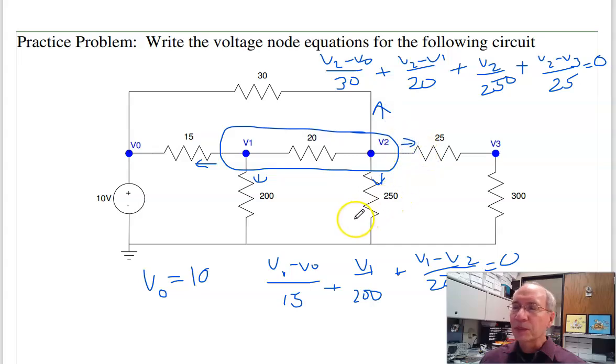And that's everyone. If I say, let's do B0, B1, B2, and the supernode, I get matrix not invertible. Again, that's telling me that I don't have 4 independent equations. I copied one of them. I repeated one. I need this 4th equation. So when you're doing voltage nodes, if you're getting a divide by 0 error, the math is trying to tell you something. It's saying you don't have the equations correct. You copied an equation. You're missing one. Trying to figure out what the math is trying to tell you, that's the challenge.